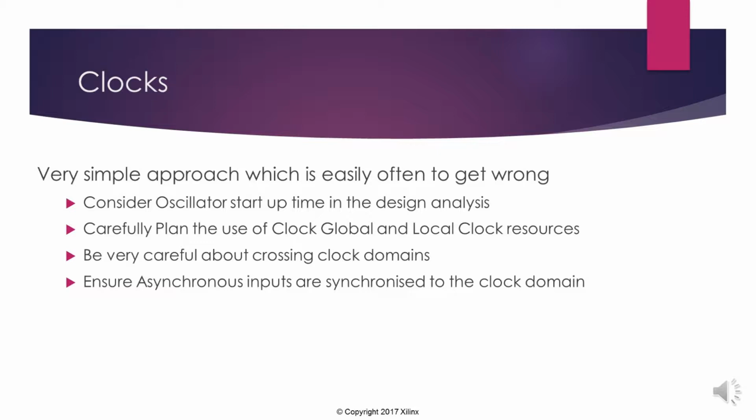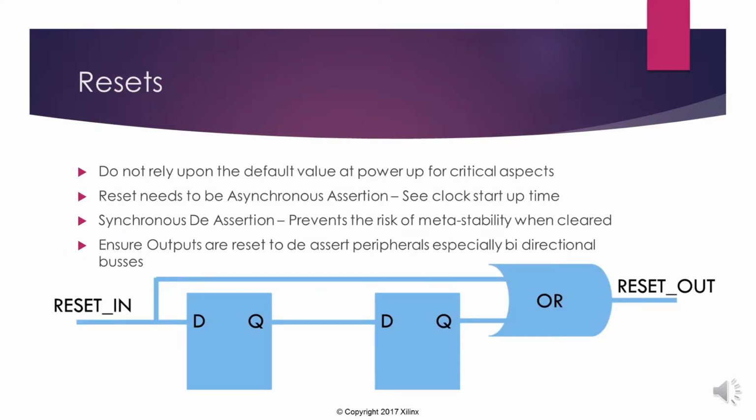Now we also need to ensure that any asynchronous inputs are synchronized to the specific clock domain, within the FPGA and internally to the FPGA. So the resets, again, there have been a few issues with resets in satellites in orbit, in that they'd relied upon the default power on state.